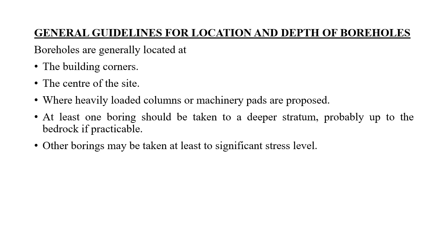So make sure that whichever borings you're taking, they should cover the significant depth or the depth of exploration based on the type of footing you have in your mind. Okay, you should not just stop at the depth where you're proposing to construct your foundation. No, you have to go beyond that depth where you're proposing to keep your foundation, and you have to explore the significant depth where your loads from the footing will be existing.